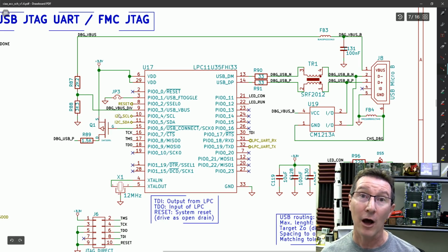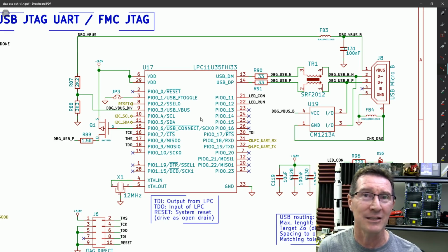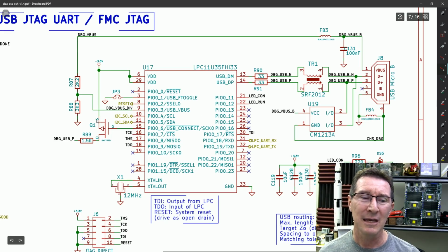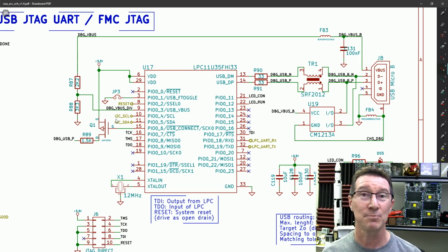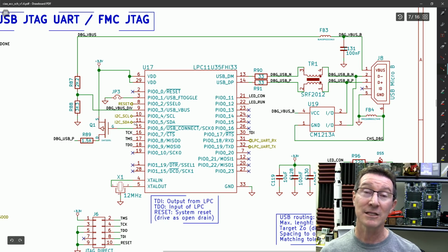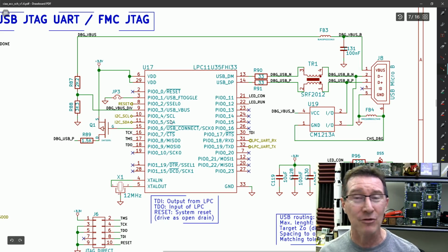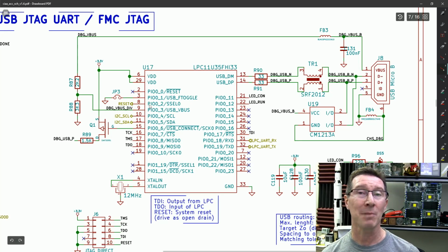If you've got a high power transistor here that might cost 10 cents, and you've got another transistor where you don't need the high power, but it costs 8 cents, do you actually need to save that 2 cents and then have a whole extra reel and go and source it and take up space on your pick and place machine, just because you didn't want to reuse this 1 amp transistor, where you only needed 100 milliamps and you chose another transistor? Can you reuse parts like that?